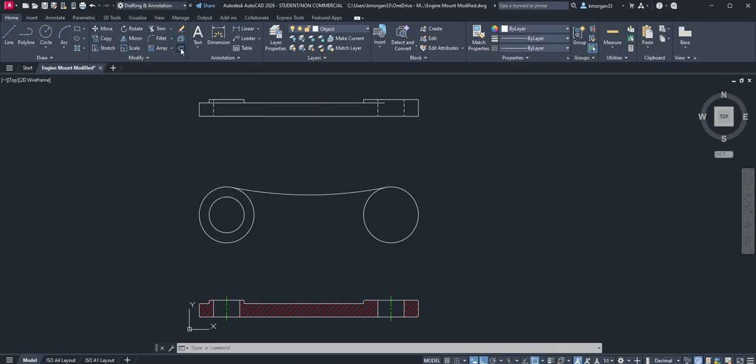Click on it. Once you click on it, you will go into offset mode, and of course, pay attention to your command line. Your command line should be saying "Specify offset distance or [Through/Erase/Layer]" prompts. What we want to do is enter 24, straight in.